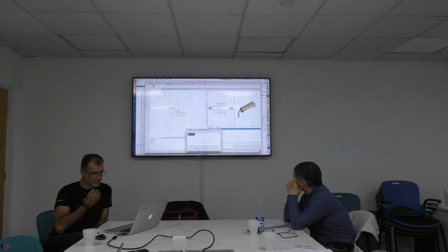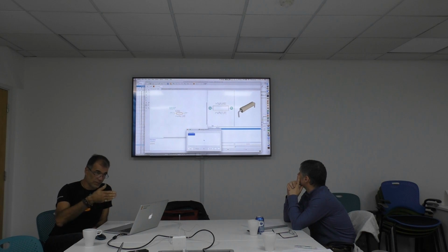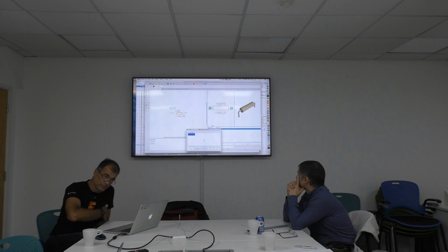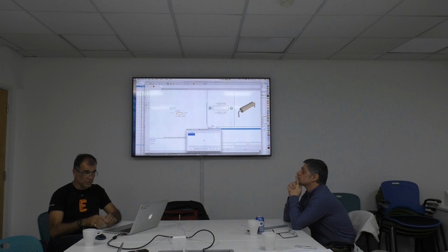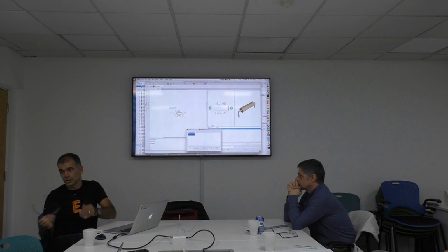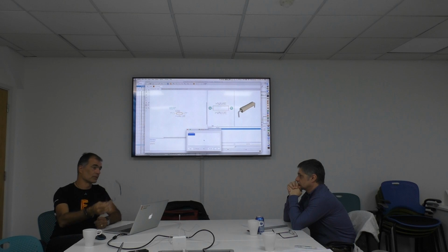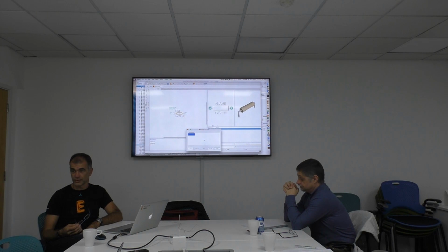Attributes, there's nothing defined. A manufacturer part number, maybe tolerance or something like this, but I would have additional information to this component. Some put prices in, I wouldn't do this, but whatever you have, the color, if it's an LED, as an attribute color, red, blue, whatever. All of these attributes will or can appear in the bills of materials. So you see simply additional information which helps maybe in the ordering process for the guy who has to order the stuff.